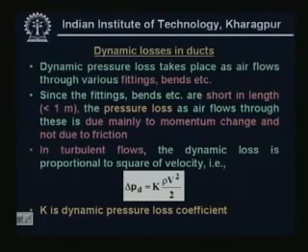Momentum changes because air either changes its velocity or changes its direction. Normally the fittings, for example bends, sudden enlargements or contractions, etc., are short in length, because rarely does the length of these fittings exceed 1 meter. Since the length is small, the pressure loss in these fittings is mainly due to momentum change and not because of frictional losses. That means the major pressure loss is because of momentum, not because of friction.